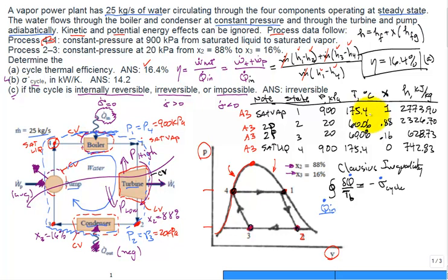Aha. Now we need those temperatures, don't we? But we don't just use the degree C. We have to convert the temperature to Kelvin. So you can convert this temperature, which is a high temperature for the boundary that the boiler's operating at, and it's 448.55 Kelvin. That's our T high.